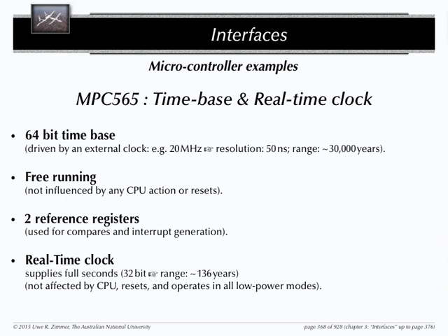Yeah. This is one of the first questions which are actually asked if you design a real-time system. What is actually my real time? Can I generate my time myself and call this my real time? Or do I have to synchronize and communicate with the rest of the world? Do I have to agree maybe with a bunch of other controllers around me about this time? Or do I have to agree with some time committees someplace what the time is? And the design of your real-time system depends to a certain degree on those decisions which you make early on. So your question is perfectly right. You have to be very conscious about what is my definition of time, where do I get my time source from.